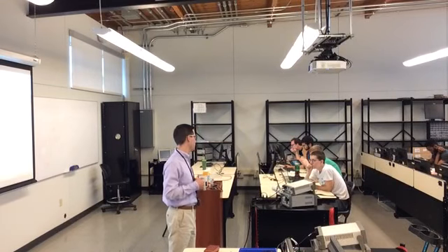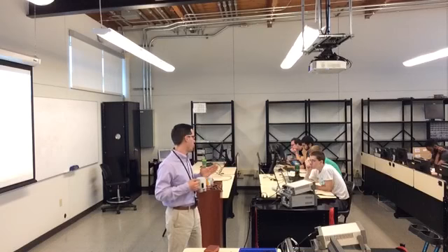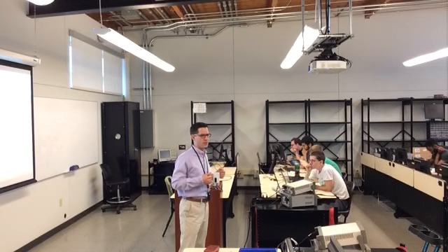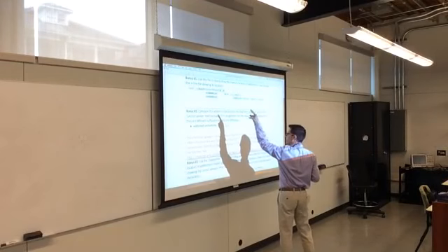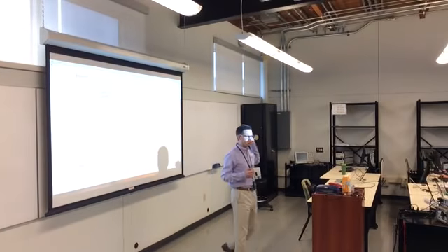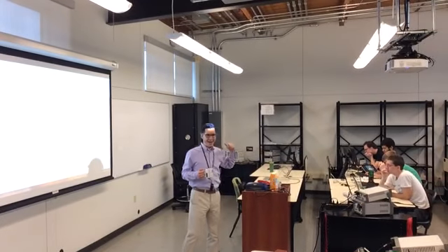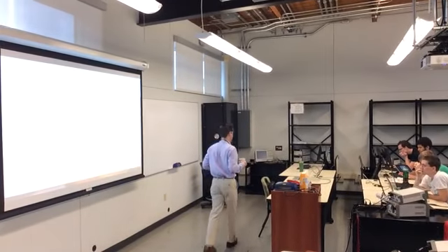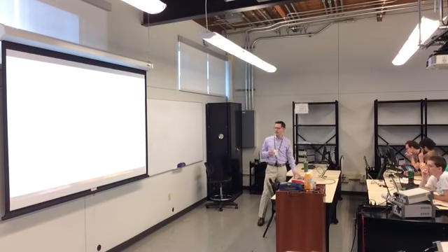The lower bit of a function pointer is set to 1 if it's a Thumb instruction. So even though it's listed at 2E8, the lower bit is set to tell the processor that I want you to go to this location, but it's actually of a different instruction type. Not an easy thing to figure out, but if you Googled around and found out that there were 2 instruction sets, you could have figured it out.